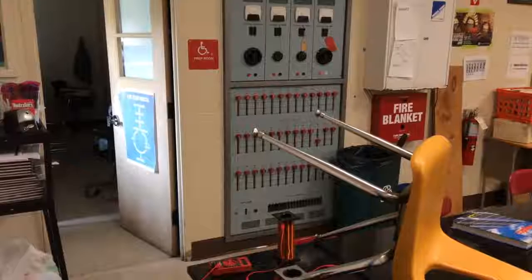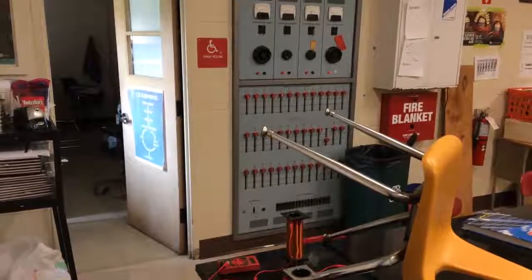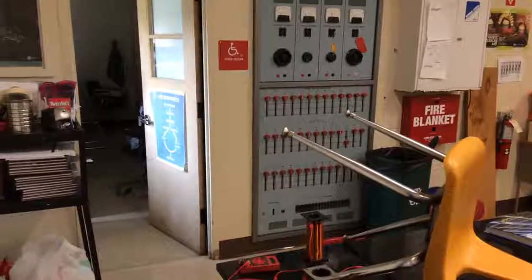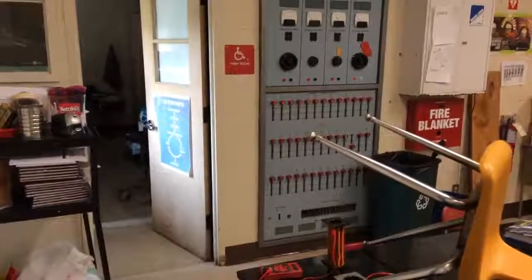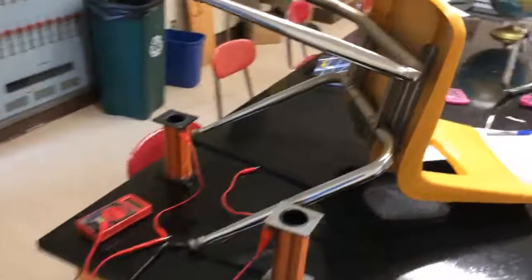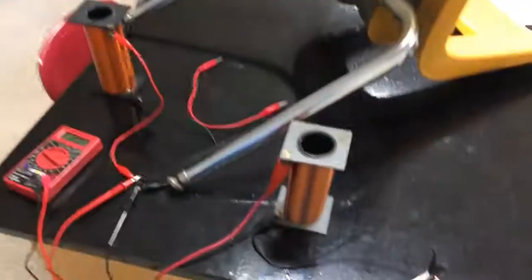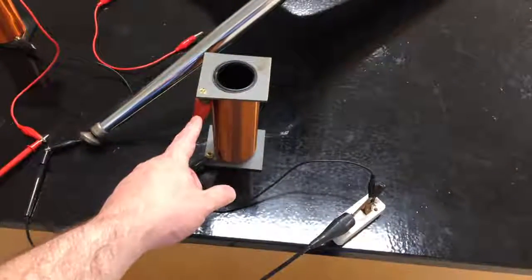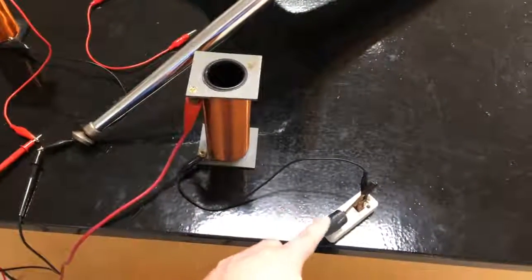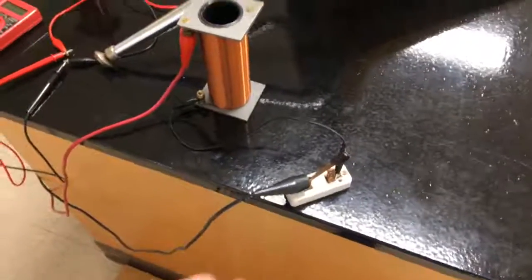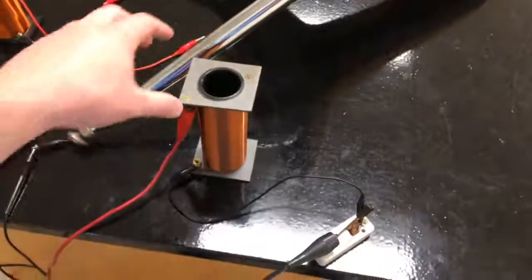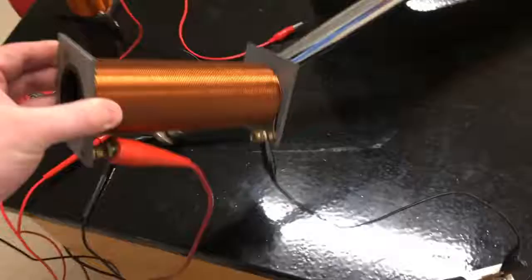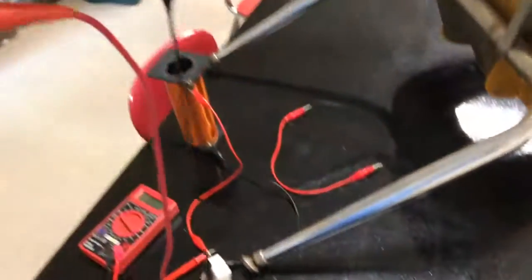So I'm going to use the DC lab power supply to show how a transformer works, and one of the issues with using the DC that Edison wanted to use. So I've got 5 volts on the lab power supply. I've got this old chair with steel legs. And to this coil of wire, I basically have the positive from the lab power supply hooked up, and I have the coil also hooked up to a knife switch so that we can turn off the electricity and turn it back on. There's plastic inside here. There's no electrical connection other than to the power supply and the switch.